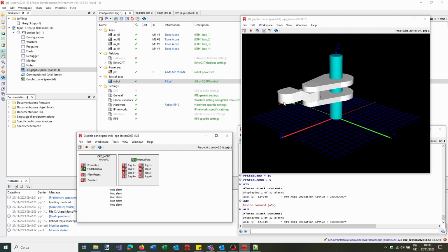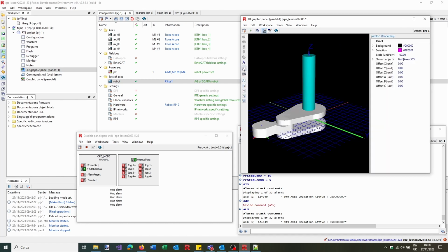One important thing we would like to have is a trace of what the robot is doing. It's very interesting to see the path while the robot is moving, mainly in automatic and it's so fast. We still want to see what kind of position have been touched by the robot. So we have this, the point strip. I use it, and here in the point strip we can say how many points, let's say so many, 500, and let's say the distance between one point and the other, and okay, 2 millimeters is a good distance.